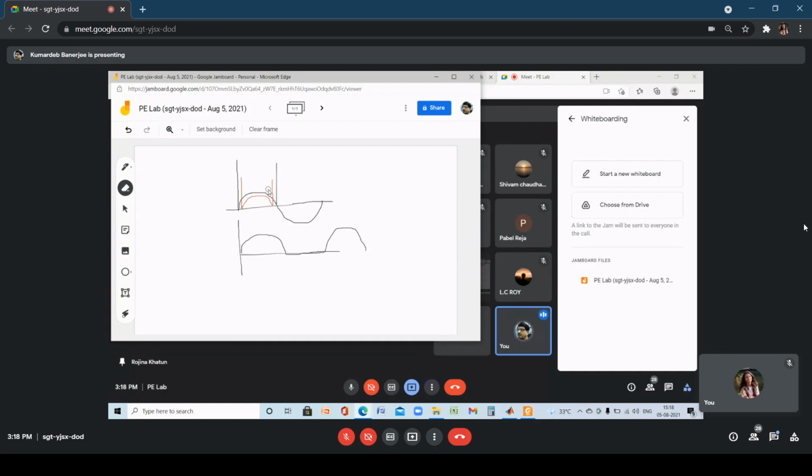So if I take that these two times are equal to Tg, or maybe T gap, then the conduction period for the diode is 10 milliseconds minus 2 into Tg. Clear? So the conduction angle for diode is not exactly 180 degree, it's something less than 180 degree. Clear?